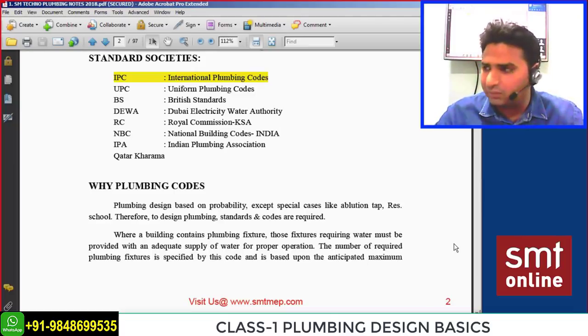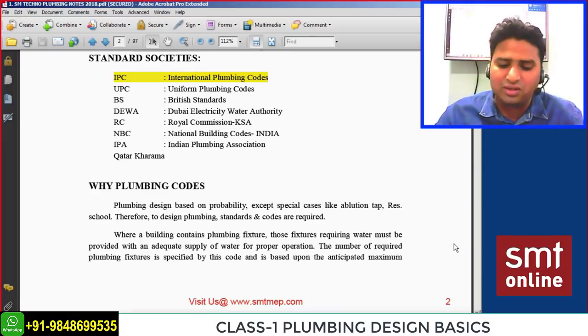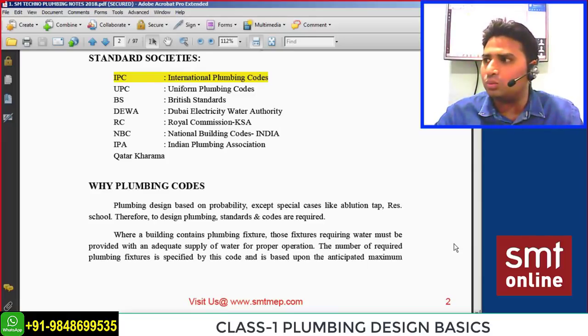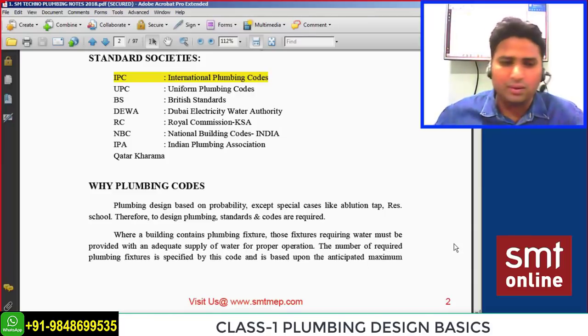Certainly, I have one more thing, that is a residential school, like a day school. Early in the morning the students wake up and they'll be using the washrooms and bathrooms. So all the fixtures will be used continuously for a certain time. That's also one peak demand. So except for these special cases, the rest of the projects I'll be dealing with the probability demand. I hope this is clear online.